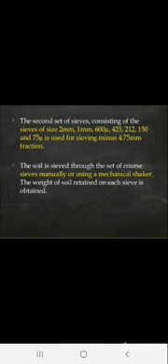The soil is sieved through the set of coarse sieves manually or using a mechanical shaker. So we have two choices. The very first one is manually, where we can sieve by manpower or simply by hand. The other is the mechanical shaker. There are machine vibrators in laboratories, and you can shake well for a certain period of time. Okay, so the weight of the soil retained on each sieve is obtained.